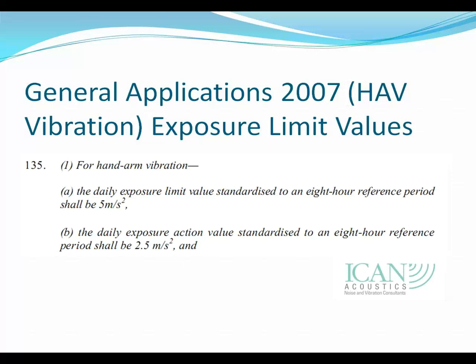So, for example, if you had a powered hand tool, you would be concerned with the trigger on time. If you take an individual using an orbital sander at a facility, it's unlikely that an operator will use that particular piece of equipment for 8 hours solid. You're talking about work breaks, rest periods, and so on. So it's based on the likely exposure over an 8-hour period, and in some cases that might be as low as 5 or 6 hours per day. You need to keep that in mind.